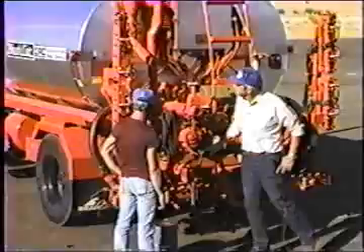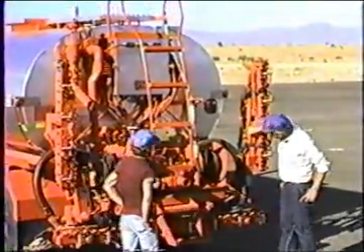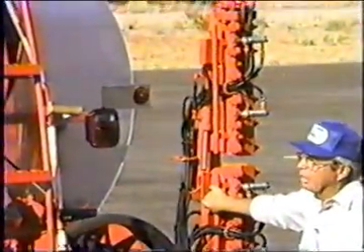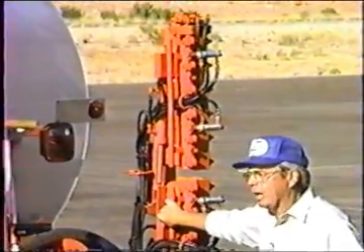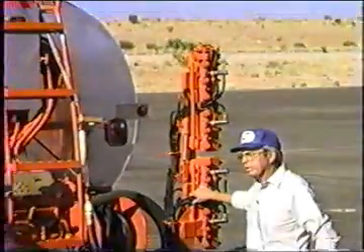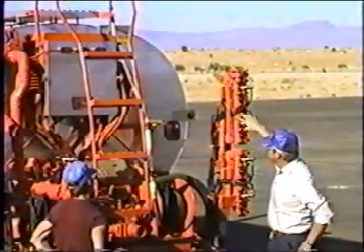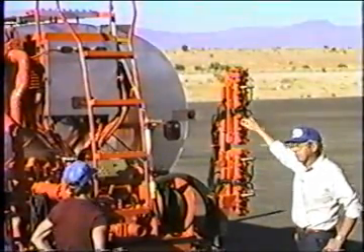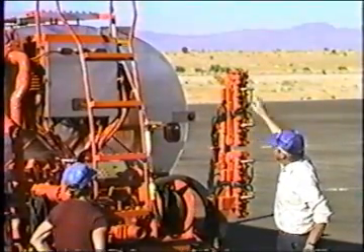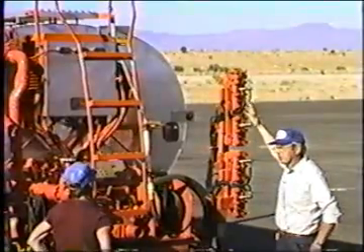Pins in the wings. On the wings, there's a little box right here, and a little box here on this double fold wing. This is a tilt switch. It's a mercury switch, just like an electric heater has. If you tilt the heater over, the mercury runs out of the switch and turns the heater off. These are arranged so that when you pick the wing up, it cuts the circuitry to the valves on the wing. That is, this one cuts the circuit to this cylinder and the marker cylinder, so that they cannot spray when they're in the vertical condition.